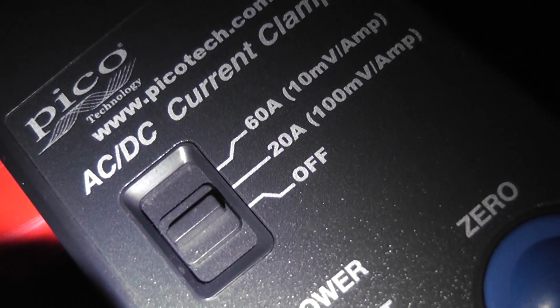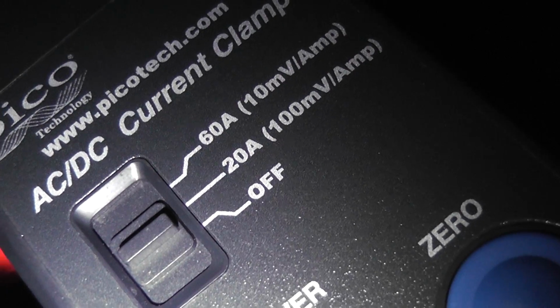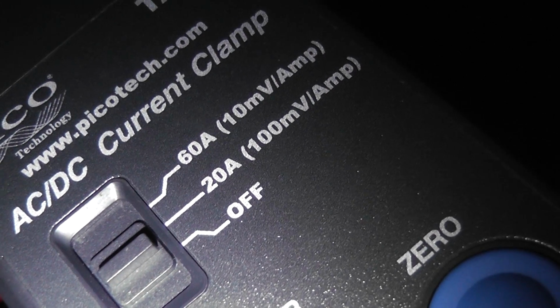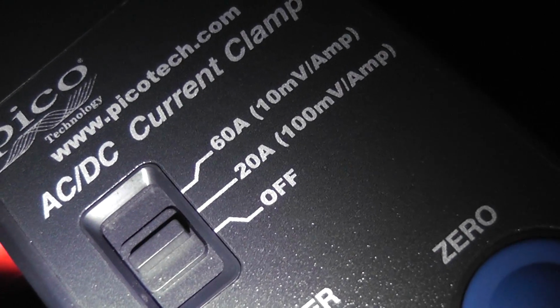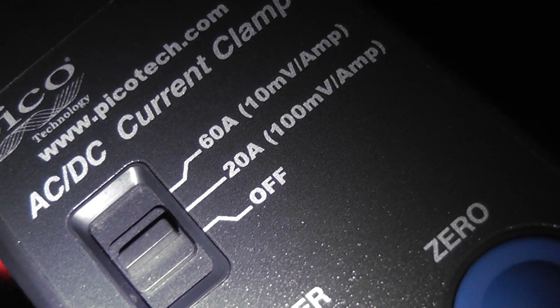Okay, I'm under the dash. You see the dark blue with a light green wire is our wire for our ignition coils. I'm using an amp clamp, and it's set on a 20 amp scale. And our 20 amp scale is 100 millivolts per amp. If you were using a voltmeter, we have a scope that does the conversion for us. So that'll be our first channel. We're going to look at all of the coils firing from this location. It's just an easy place to do it, which is why we picked it.